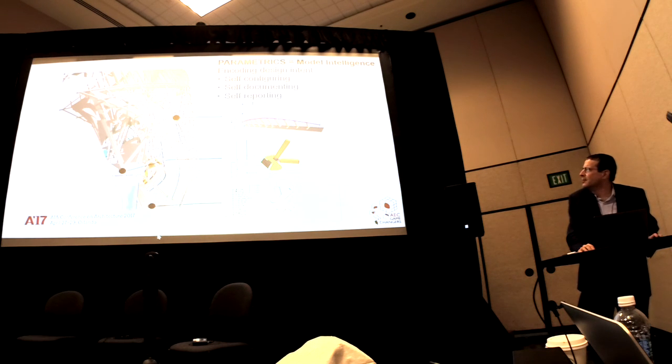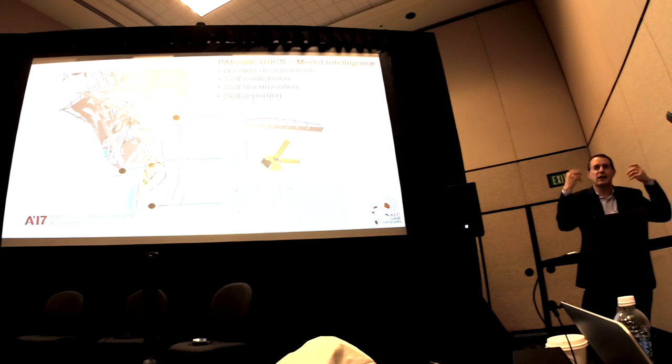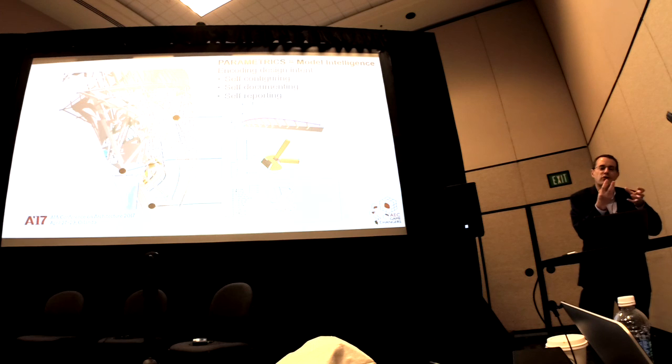I'm going to skip through most of this, but once you do that, you have the ability to throw in parametric objects that are plugged into this hierarchy and accept inputs from the higher level. So if I have this exterior envelope surface and a structural frame, I can start plugging in intelligent objects, equivalent to families in the Revit vernacular. These objects can be responsive to their input conditions, so they can adjust themselves. And when the overall top-level hierarchy changes, these objects can adjust themselves.